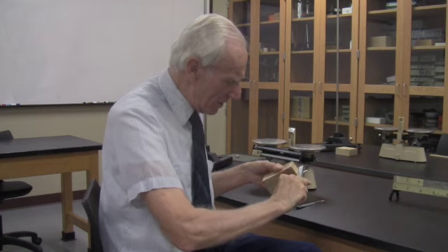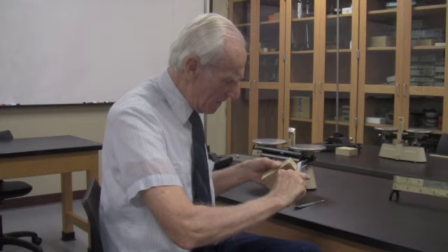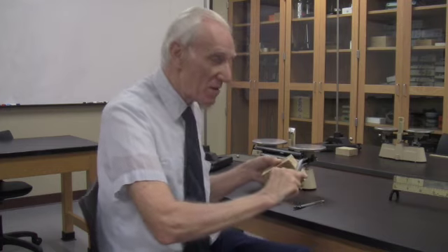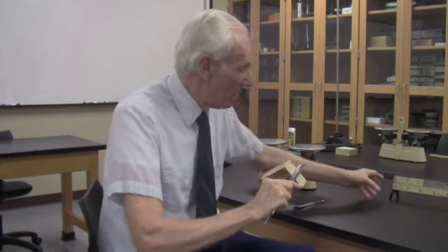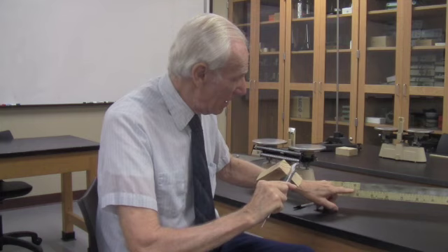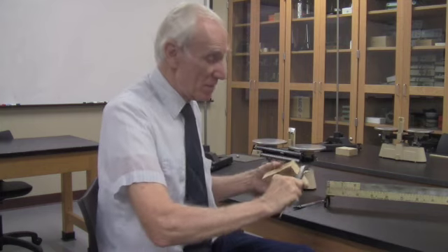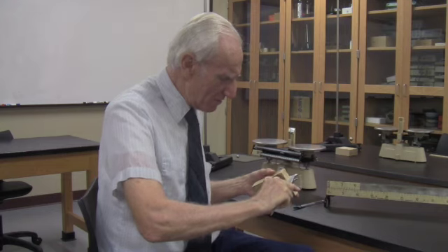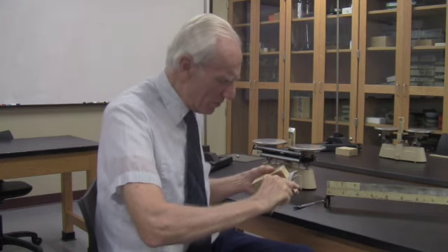And so you look up and down the scale, and you find it's got 50 marks. Each one of those marks is actually 0.02 millimeters. And so you can read to the nearest 0.02 millimeters by lining up the marks. As we saw over here, the mark that lines up best, that's the mark you're looking for. So I'm looking for that mark, so it's 3.6 something, and it's pretty close to 3.7, so I'm going to